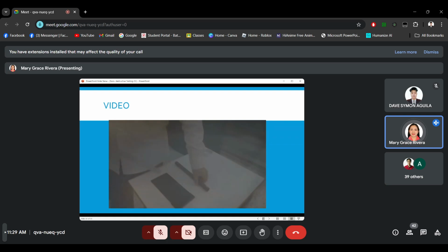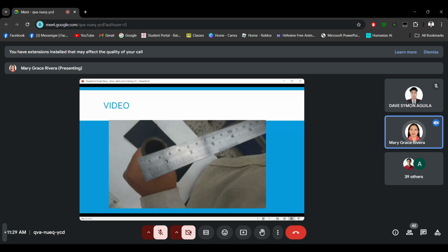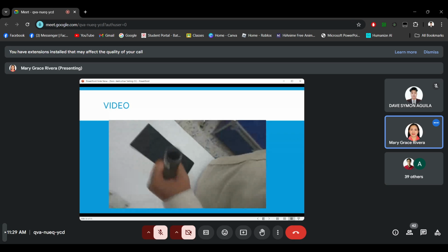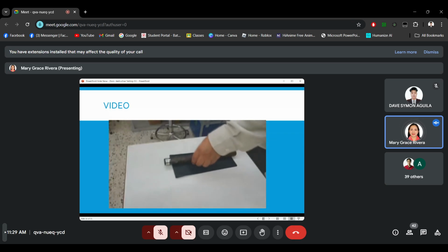Fourth technique is double wall double image. It should be used for pipe that has equal or less than 3.5 inch of diameter. The technique can be used in which the radiation passes through two walls.